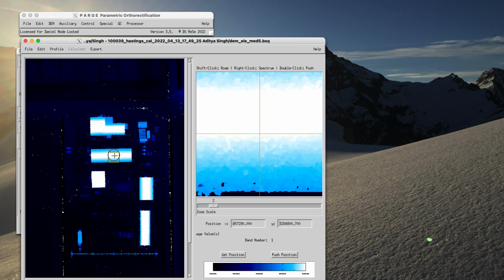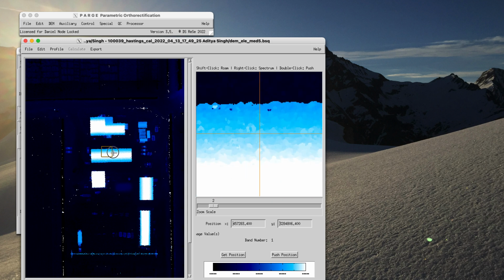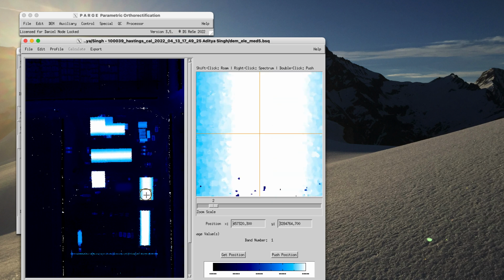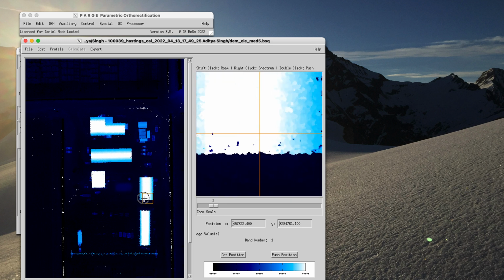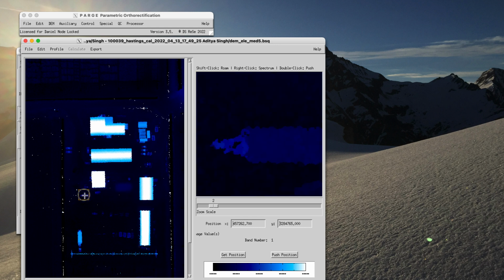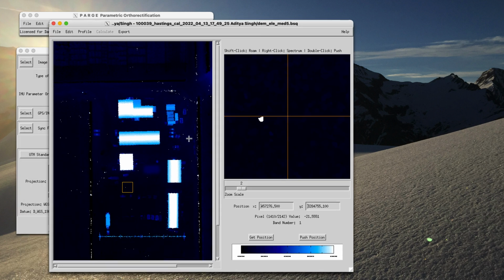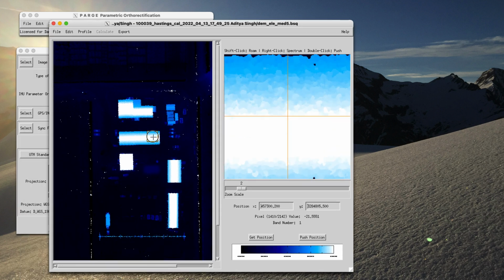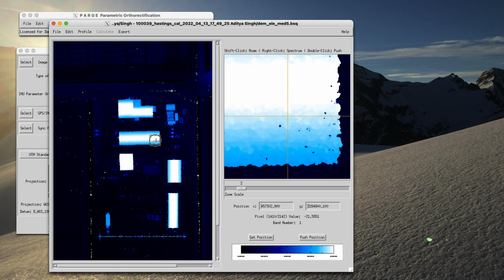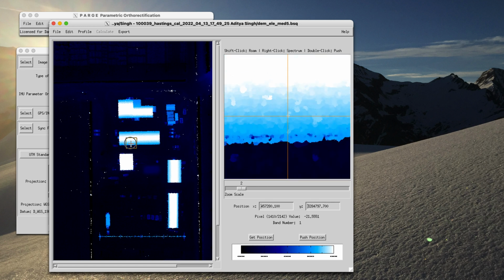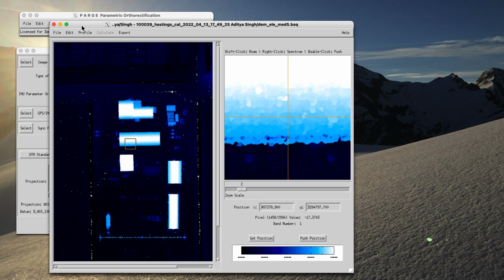So if you look at the DEM, that's a digital surface model of this area. So these are buildings, and there are some holes in there, so some filtering is really required for this kind of surface model. And maybe some more preparation would be required to get rid of certain artifacts. In this roof, you see there are some artifacts in the surface model. So this may need more elaboration to get a really good surface model to work with. But to start with, that's fine.